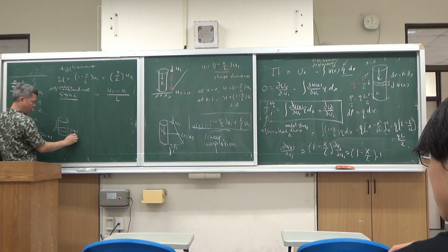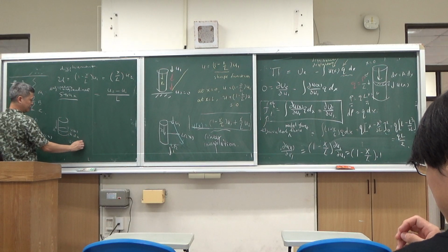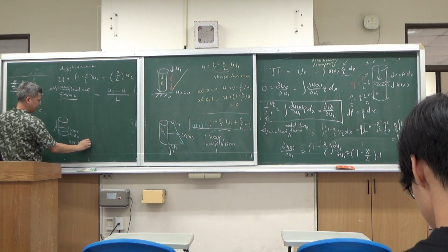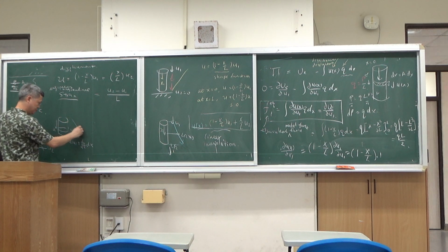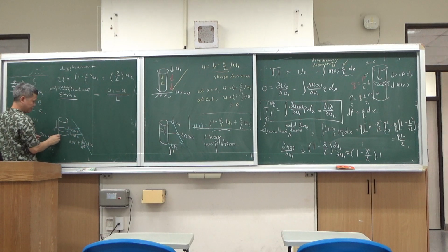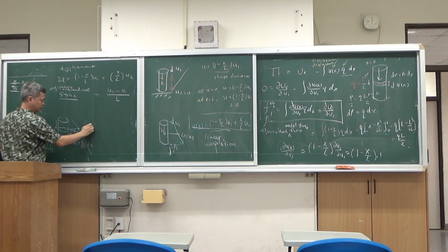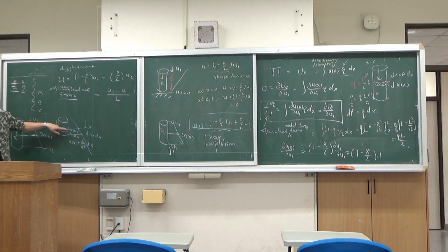And then after the small piece, you might have displacement u(x) plus du/dx dx. Do you see? This is a small slice, a slice of a bar. This point is x, the lower point is x plus dx. Then the displacement goes from u(x) to u(x) plus du.